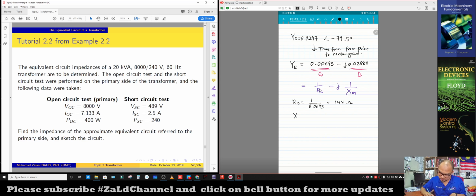And XM similarly is 1 over 0.02888, which is 34.63 ohm. All right, so we get RC and XM as the parallel branch from the open circuit test.